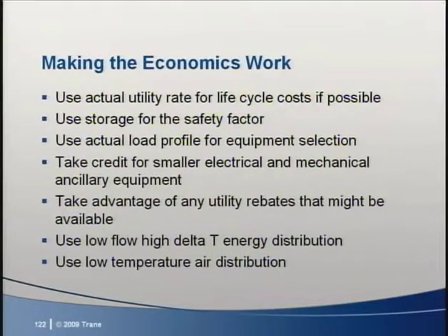Make sure that the load profile being used does not have extra safety factor already included in the hour-by-hour numbers. Using the actual design day load data in a load profile allows the equipment to be selected as a system and lowers first cost. Another way to say it, and it's paradigm shifting, is to lower the chiller size by 20 to 40% and add storage for the safety factor needed on a design day.